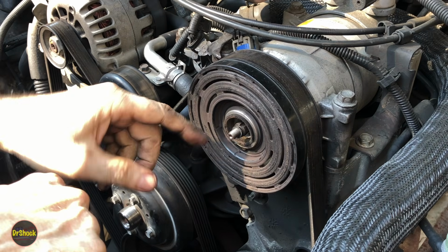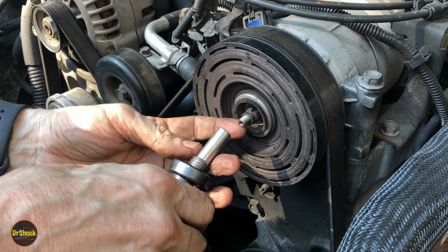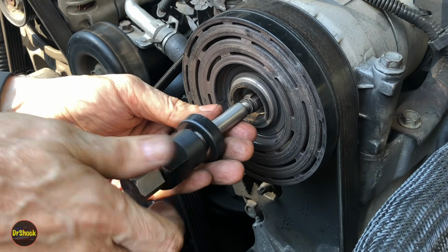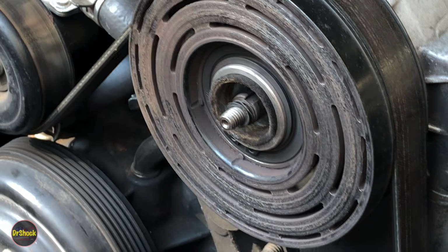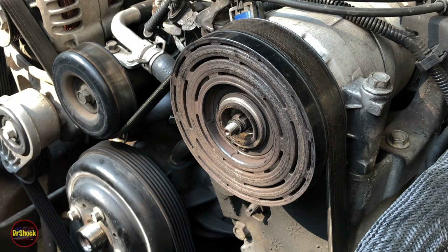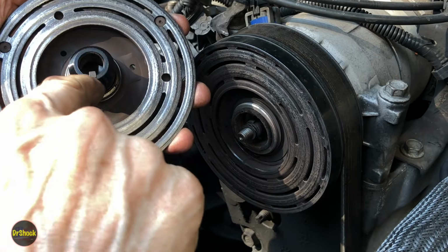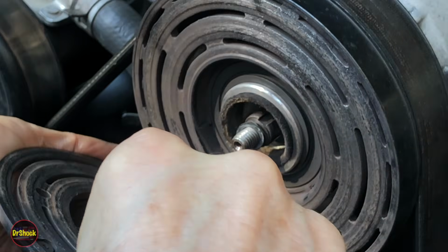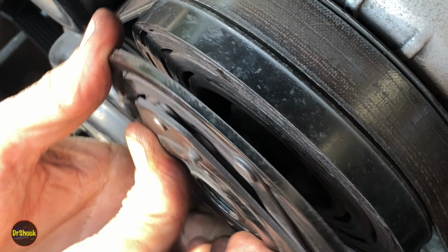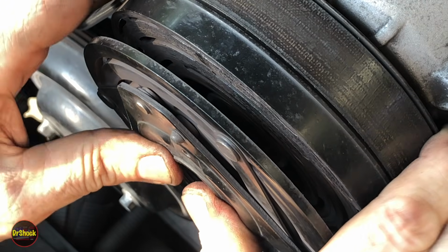All right, with the belt on, shims on, felt washer on, we chase the threads on the stud, make sure our custom M8 tool fits on okay. Now we've got to get this guy on far enough to use the tool. Make sure your keyway is installed, and we've got to get the keyway above the shims and into the notch on the shaft. And you'll know you got it lined up if you can partially push it in by hand. Just like that. All right.